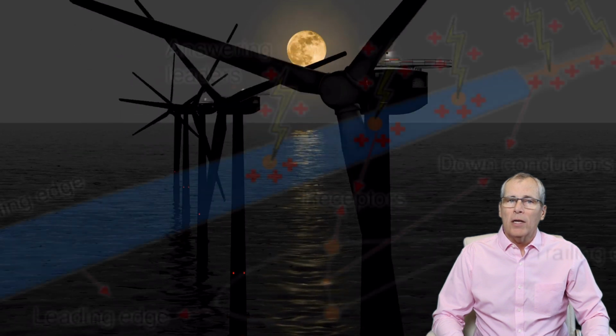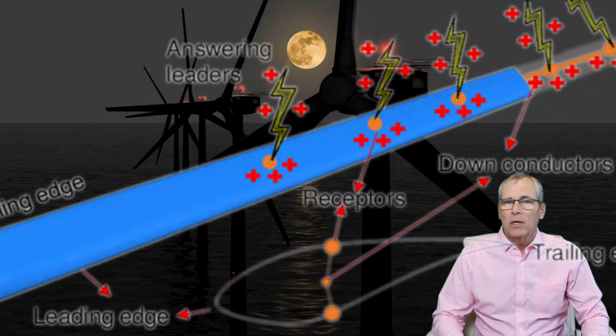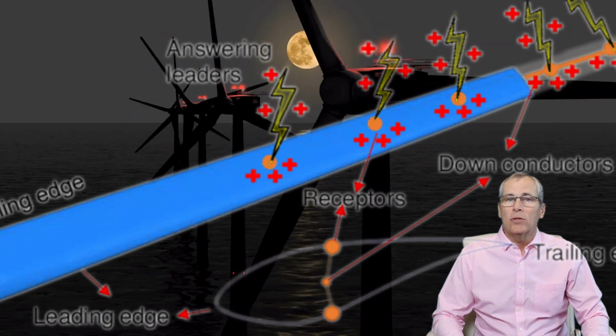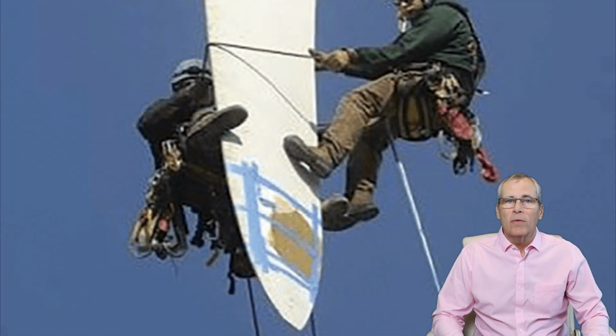The dilemma arises from the fact that the paint or coating applied to the embedded targets can reduce the conductivity of the metal, which can in turn reduce the effectiveness of the blade lightning protection system. This can lead to an increased risk of damage to the turbine from lightning strikes.